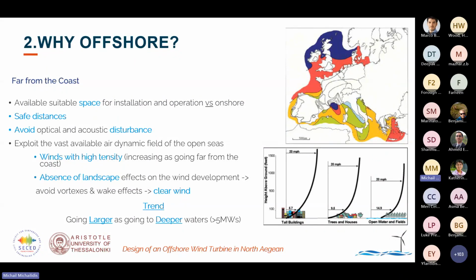The reasons why we should go offshore start with the available space that we have for both installation and operation. We can ensure safe distances between the wind turbines, avoiding the wake effects between themselves, and having a clear wind profile each time to be fully exploitable. We can avoid optical and acoustical disturbance from the wind turbines, while we can exploit as well the winds with high density, which are increasing as going far from the coast.